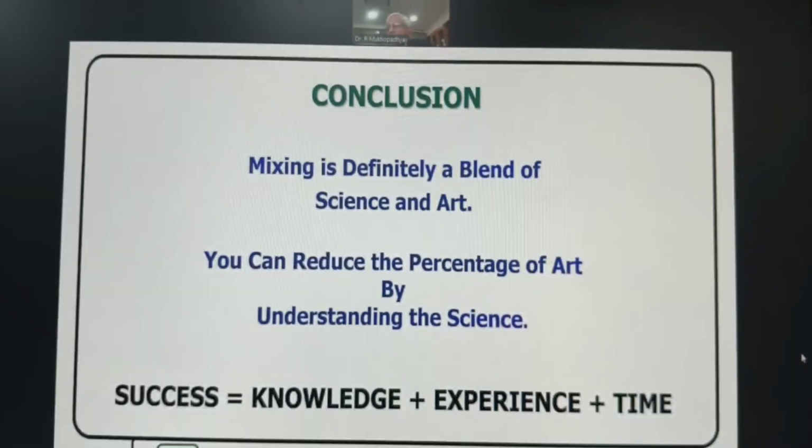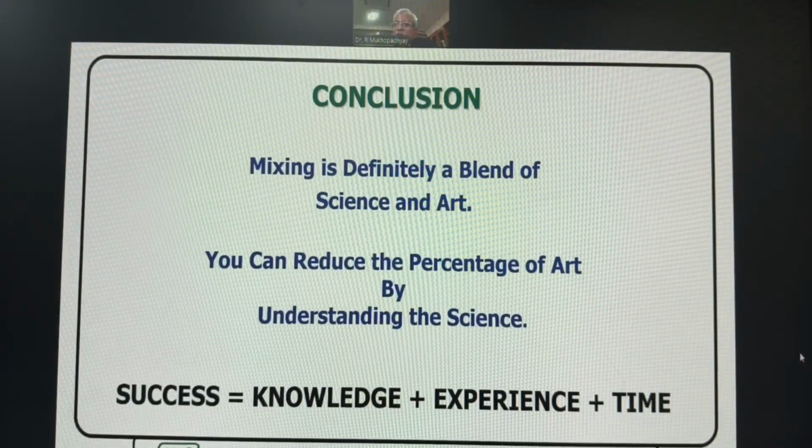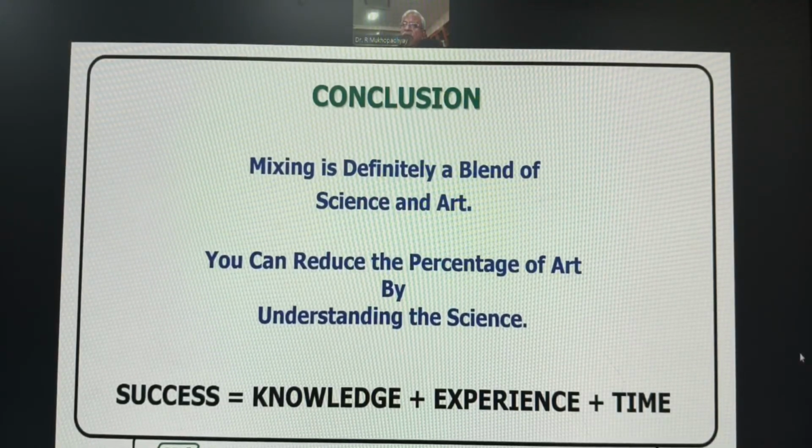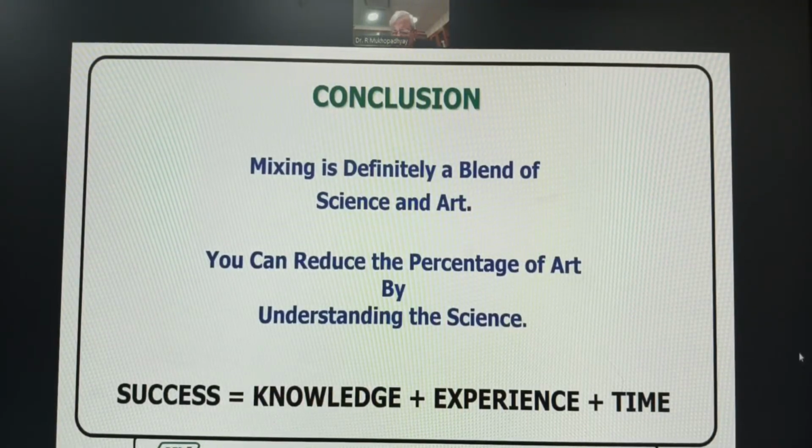Then, if you find that the bloom is yellow or white, and if the yellow one contains sulfur, put one drop of carbon disulfide, and if it dissolves, you can tell. Generally you get a ring type structure. So if it is a white ring, zinc stearate, automatically you can easily find out the acid basic thing. Similarly, if you have certain antioxidants and other brownish stain, you scratch it and do the TLC. So in a really small laboratory, all these things are possible to understand the science.